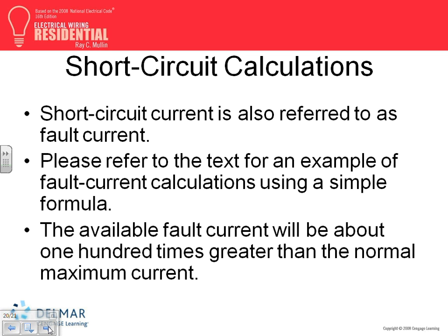I think the assumption right now is to move to circuit breakers because of tampering with fuses. People, if it trips, don't have the right size, so they put a penny in behind it and lock it. Now you can burn the house because of that.